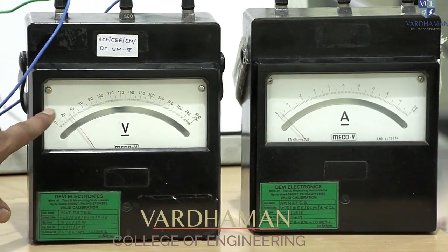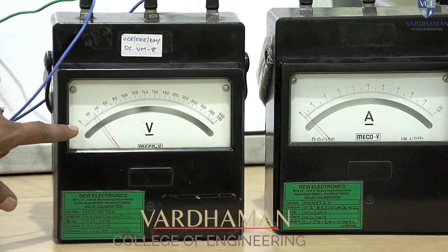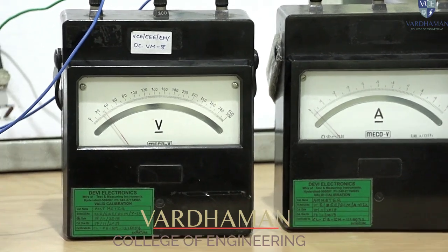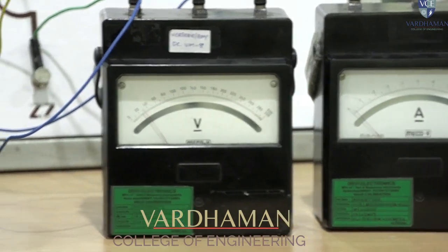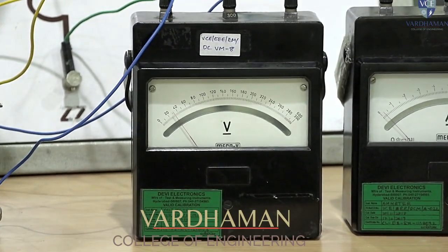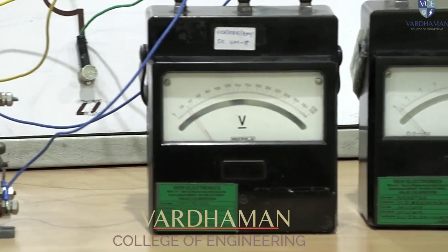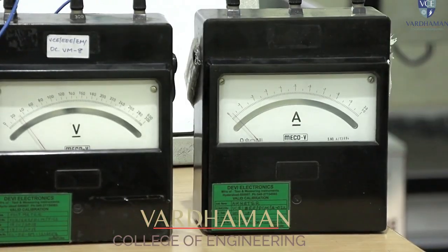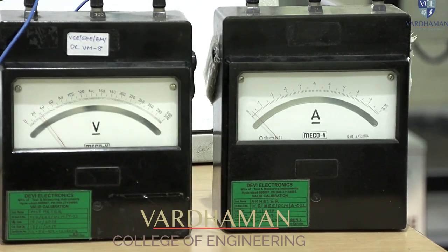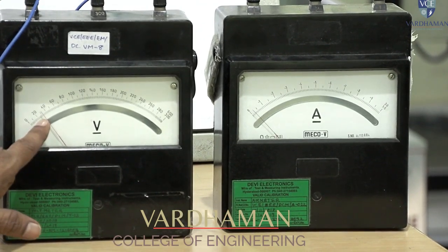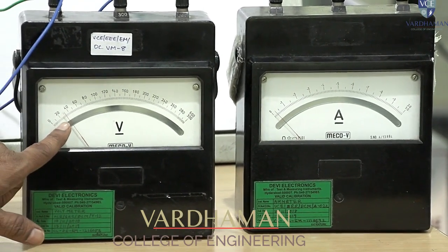The voltage never starts from zero in this experiment. The reason is that your magnetic field coil, which is this electromagnetic field coil, has an iron piece possessing a residual magnetic property. So the magnetic property is there, and a little amount of flux is induced. By changing that little amount of flux, we initially start with 25 volts.